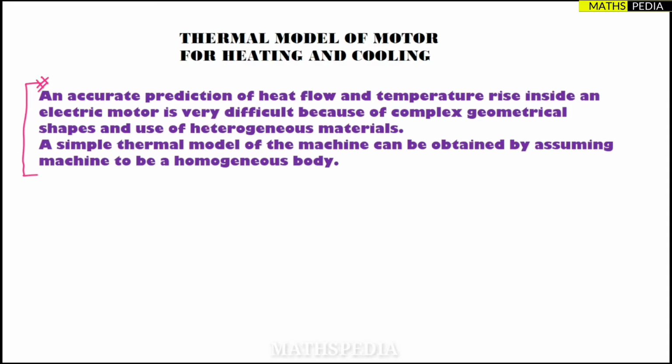See, basically in any motor or the machine, heat flow and temperature rise will be there. Okay, so prediction of that we have to do, right? Prediction of that is very difficult in any electric motor. Okay, so why is it difficult? Because of its complex geometrical shapes as well as the use of heterogeneous materials. So because of the two factors, it is very difficult for the heat flow and temperature rise prediction.